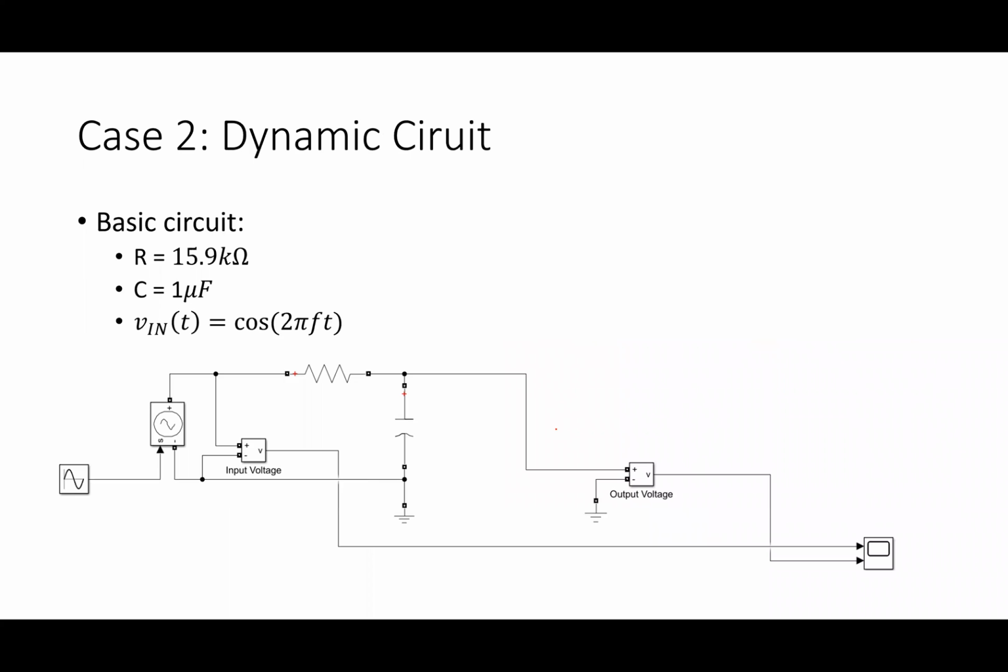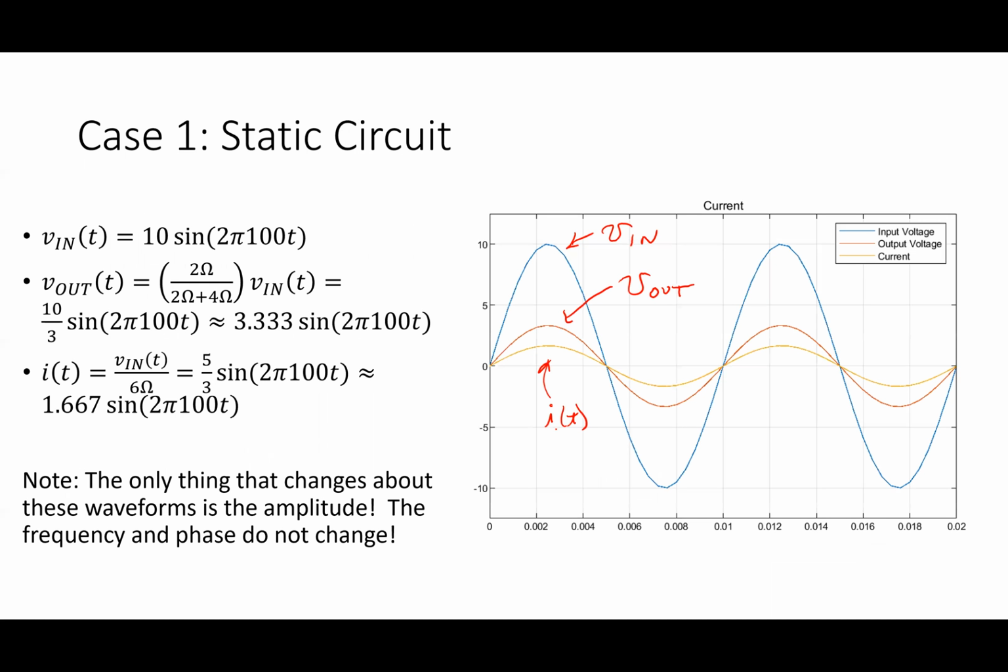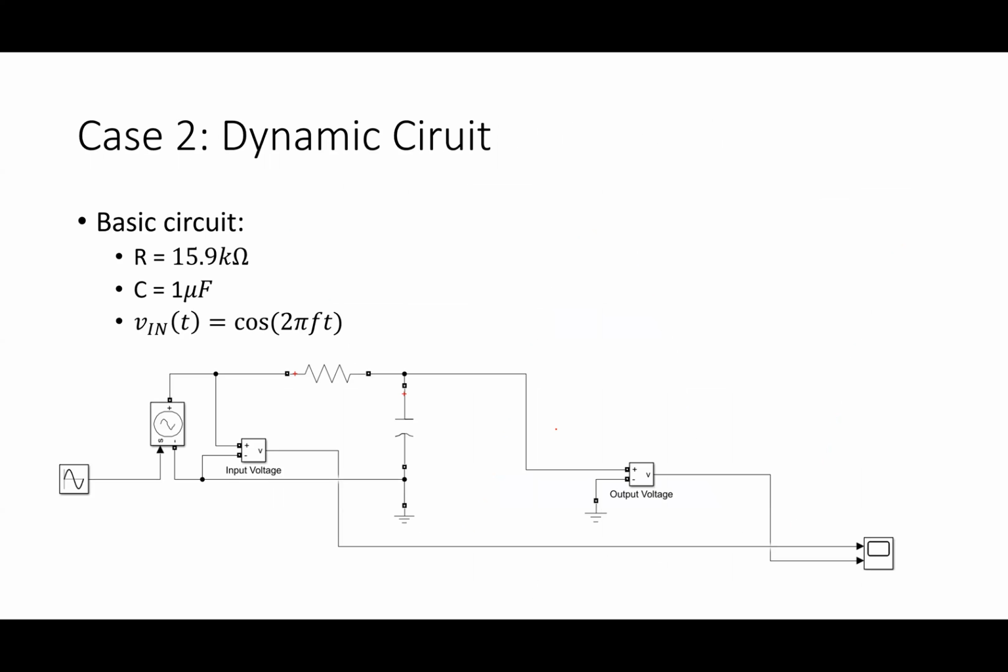So if I looked at this circuit, right? This circuit was a little bit different. Now I replaced that resistor with a capacitor. And I guess before I move on to that, what's true about the phase shift here between the voltages and the currents? Is there one? They're all in phase together. There's no phase shift. That always happens if I have resistors, and only resistors. Now we looked at this circuit here, right?